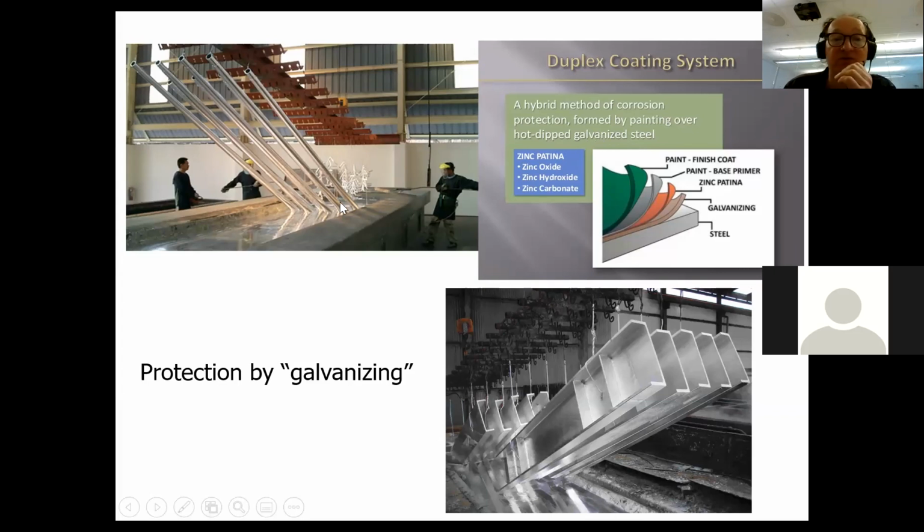And here you can see these people doing just that. Here is a bath containing molten zinc, so it's quite hot. And these are the steel objects, and they're quite literally lowered into the liquid metal for a few seconds, and then they're pulled right out again. And the metal will stick to the steel to form a layer. And as soon as it's pulled out of the hot bath, it will start to solidify or freeze over. And it'll form crystals of zinc on the surface of the metal. But most of the zinc goes back into the bath to be used again on another object.